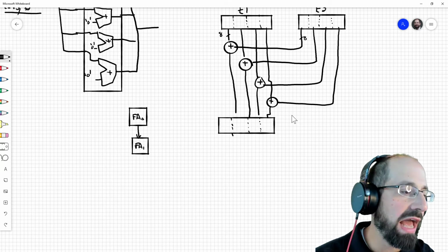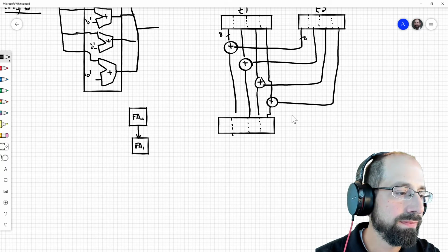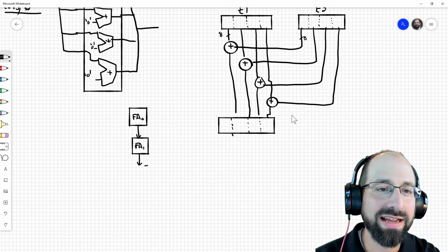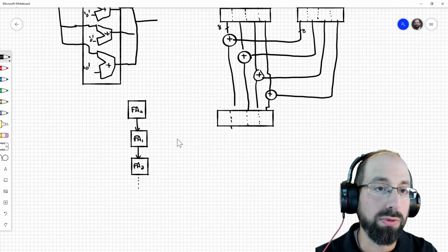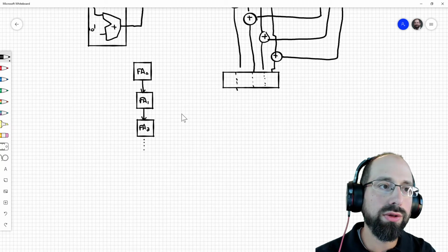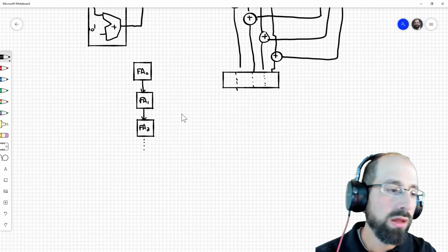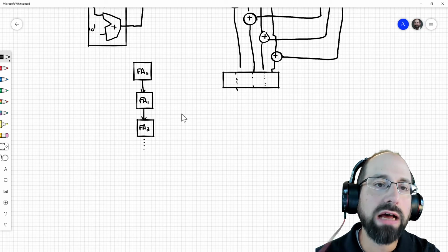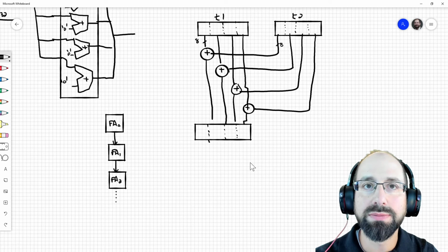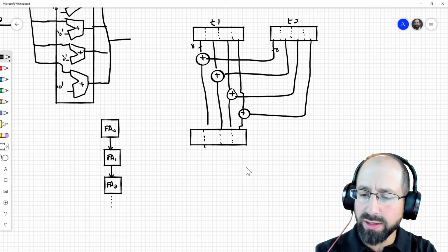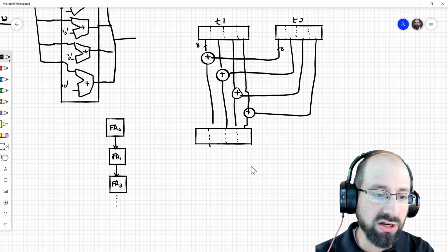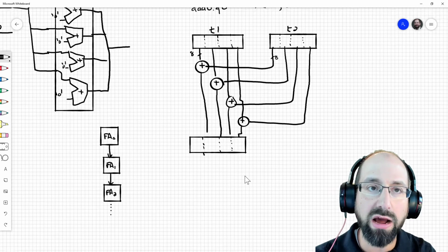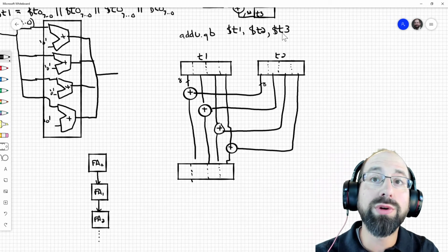In which we have these full adders that are rippling, connecting from carry out of one to carry in of the other. And that already allows us to support our conventional 32-bit addition. What if we were to want to also now support these independent 8-bit additions? Well, let's think about that a little bit. Ignoring the question about overflow and things like that for now, the DSP instruction set does explicitly talk quite a bit about that. But ignoring that consideration for now, we're treating these 32-bit values